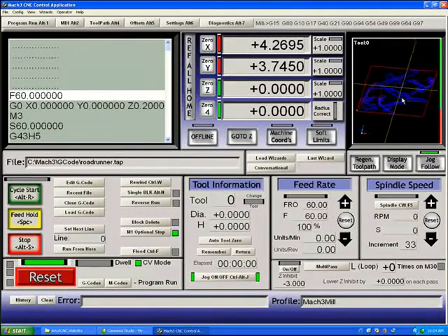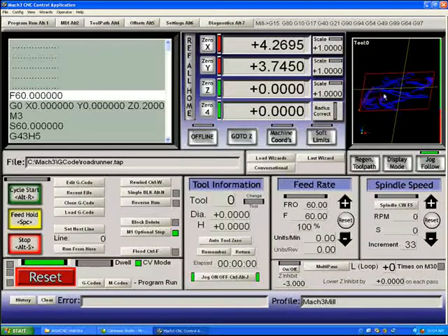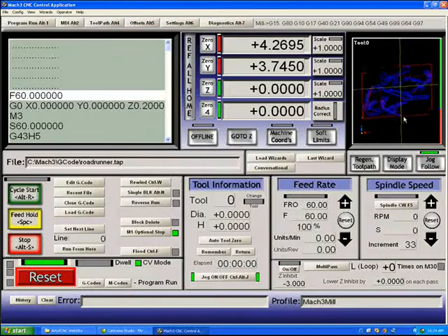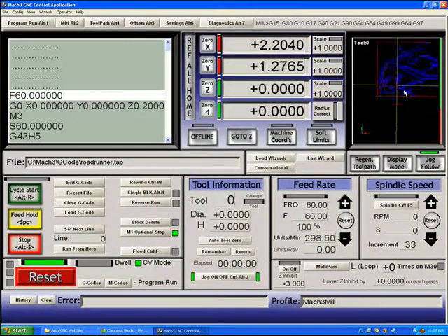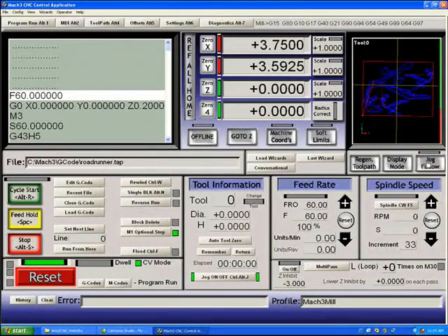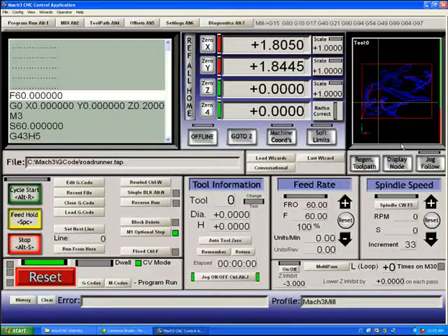Now, whenever you zero DROs, these are the DROs, by the way, digital readouts, this yellow line, two yellow lines, shows the X and the Y axes intersecting. So at this moment, my tool is centered somewhere up around this Roadrunner's foot. If I jog my axis, you can see that the drawing moves to show where the tool is currently at when I'm in Jog Follow mode. If I turn off Jog Follow mode, the lines move to show you where you would be. Again, double-clicking will reset the system.